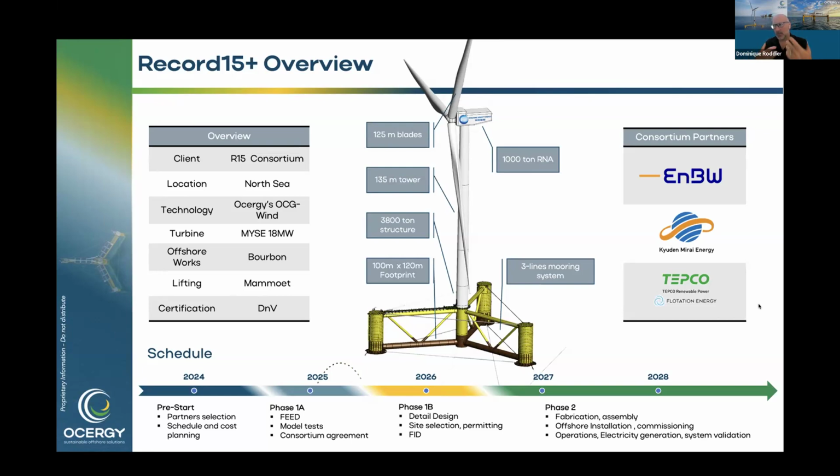But again, you also have to look at what the biggest storms are that you're going to see. If you're above Scotland, where there's a lot of oil and gas in the Shetlands, your maximum Hs is 17, 18 meters. If you're in the Med, you're at 12. So not the same structure.